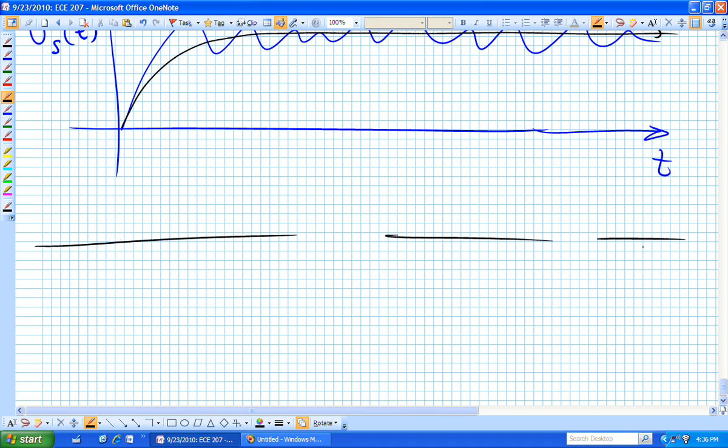And that wasn't too difficult to design, was it, in terms of build? A low-pass filter is just an RC circuit. It's first order. If you wanted to be more effective at getting rid of that noise, you might want a higher order filter, which is maybe why you want to put some more capacitors in there. We're not going there yet. We're still in the first half of chapter 4.